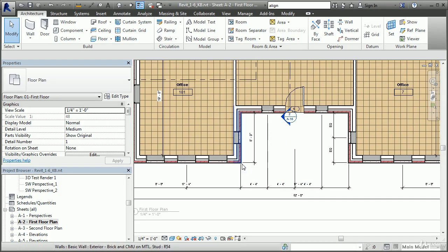Now it's really kind of fun to add all of these constraints and these alignments and locks. You do need to be careful and not put too many in. Just because you can doesn't mean that you necessarily should lock everything down or create too many constraints and alignments. When you add too many constraints and alignments, the model size will get too large, and sometimes you'll get unintended consequences. The relationships and the locks and constraints can propagate and compound across the project, so that you can change the location of a wall on one side of the building, and a window on the far side of the building might move as well.